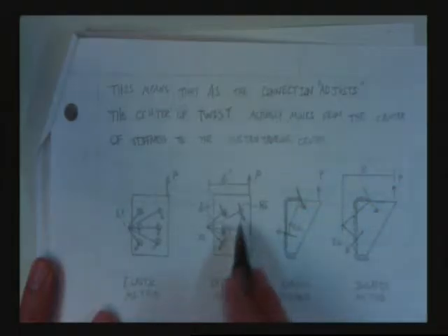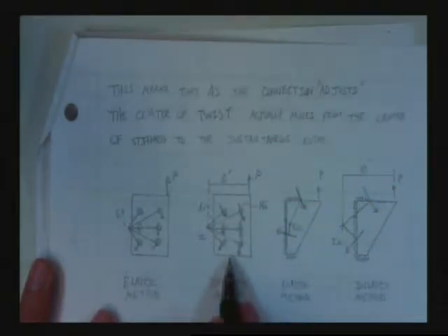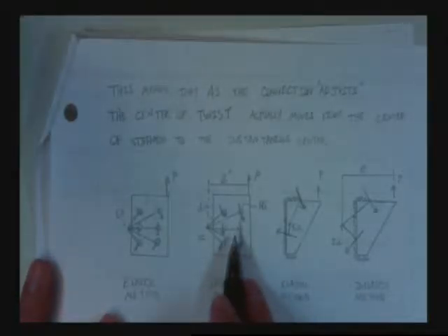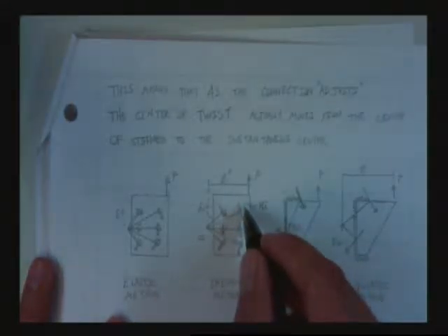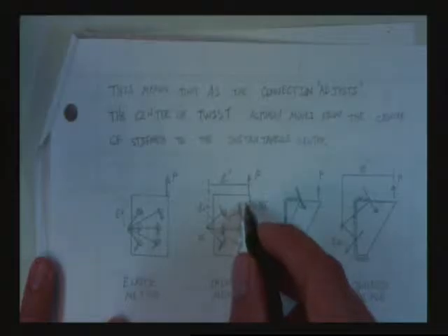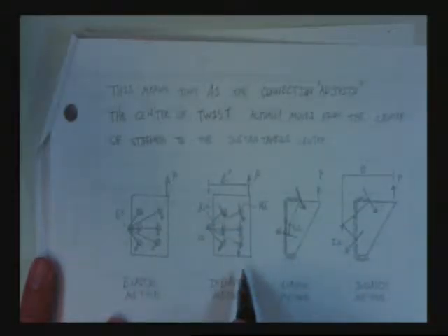And I'll ask you, what is the magnitude of each one of these vectors? The same. Right? And we even know more than that. We know that they're either going to be equal to the capacity of the bolt or the bearing and tearing capacity of the bolt. Because that's going to control, right? The bolt's either going to break or it's going to tear out the side. Or it's going to bear so much, it's going to cause too much deformation. Does that make sense?